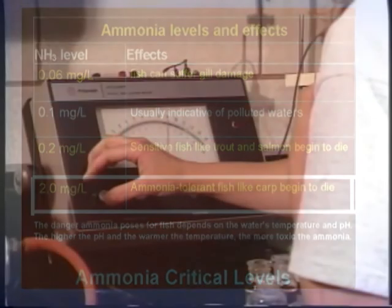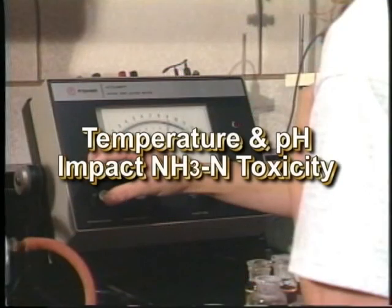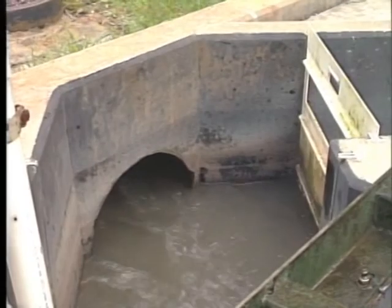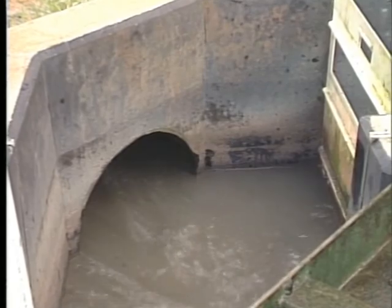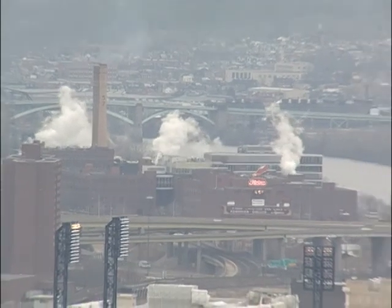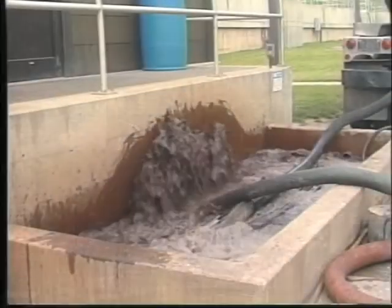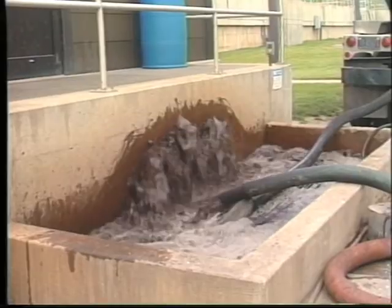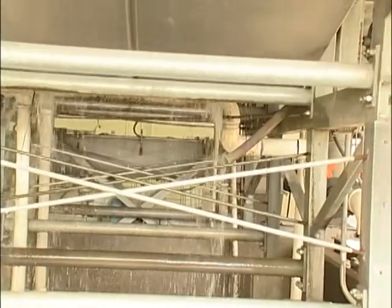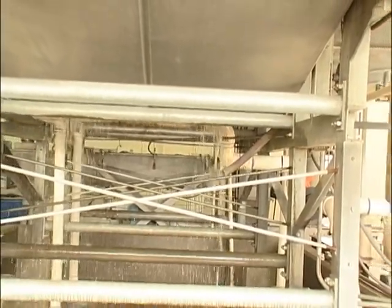The toxicity of ammonia is impacted by the water temperature and pH. Typically, the higher the temperature or pH, the higher the toxicity. Ammonia in wastewater can come from a variety of sources and is found in domestic wastewater. Non-domestic wastewater, such as industrial or institutional wastewater, trucked-in waste, such as septage, and internal recycle flows, such as belt press filtrate or anaerobic digester supernatant.